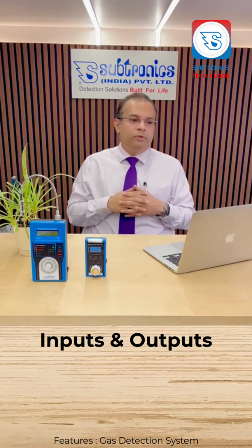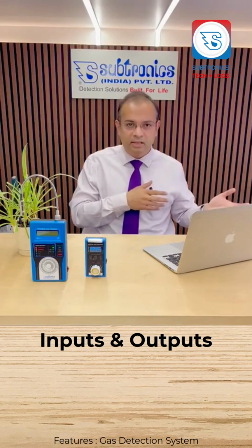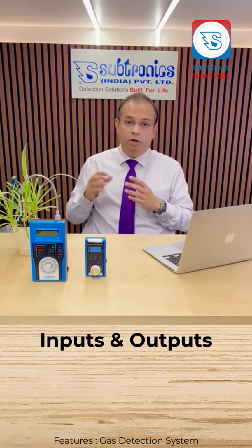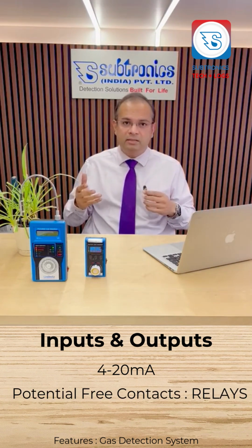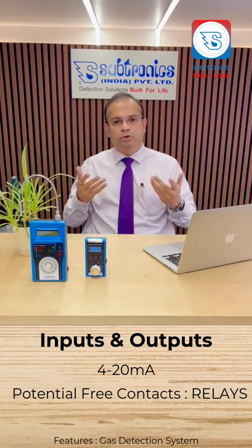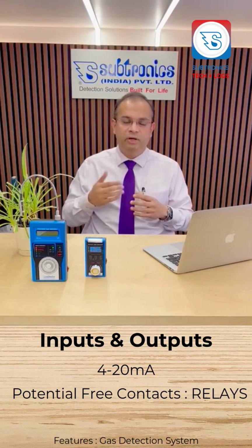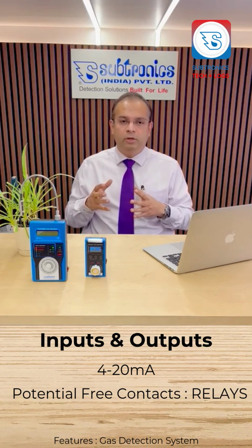The second feature of the gas detection system is the inputs and the outputs. Usually for the controller unit, the inputs are the sensors. The outputs are the ones which interact with your accessories or your control panel. These include 4 to 20 milliampere outputs and relays. Sometimes you need potential free contacts to switch something on and off. For example, at the first stage, you need the exhaust to go on automatically, which can be done using a potential free contact. And at the second stage, you want the sprinklers to start, which is also done using potential free contacts.